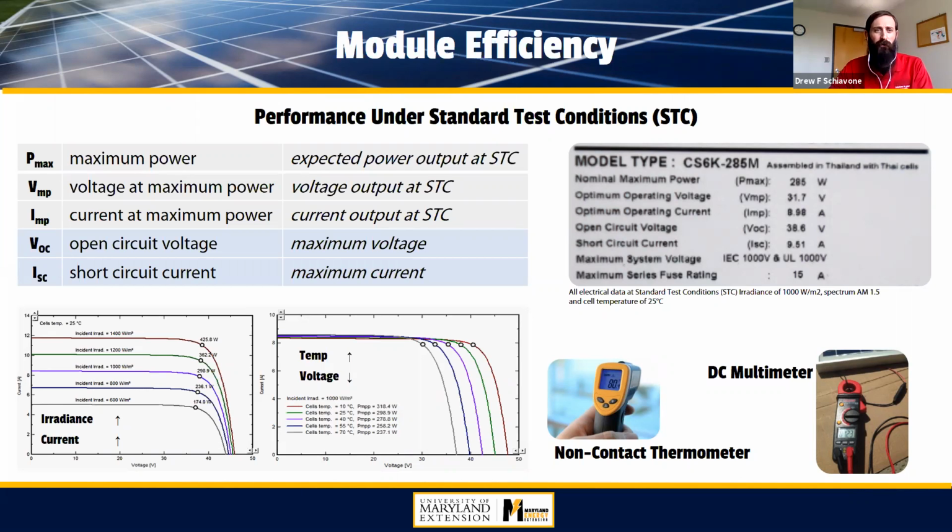power. You would get the voltage and the current, both at maximum power. Of course, those are all related. Remember, voltage times current gives you power. But what you'll see, and what that spec sheet emphasizes, is those are conditions that have been evaluated under the solar standard. And so you'll see that on every PV system, every module is going to have that solar standard. And that's important because you could make it look better if you tested it under better conditions, or you could make it look worse if you tested it at midnight. But again, it's all evaluated at that solar standard.